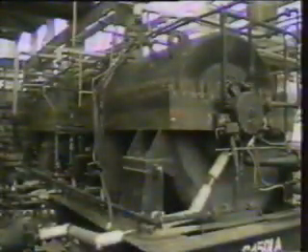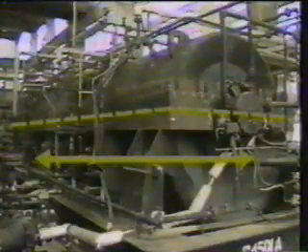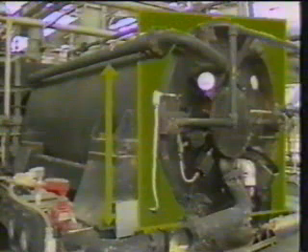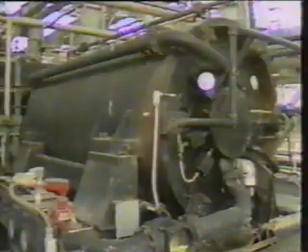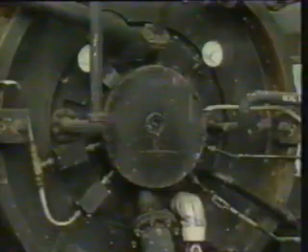In centrifugal compressors, there are two primary casing designs: horizontally split, otherwise known as axial, and vertically split, sometimes known as radial. This split in the casing provides a means for reaching the internal working components of the compressor for repair or replacement. In addition, the material used to make the casing is determined by factors such as stress, temperature, and corrosion. In the horizontally split casing, the split runs along the center line of the compressor.